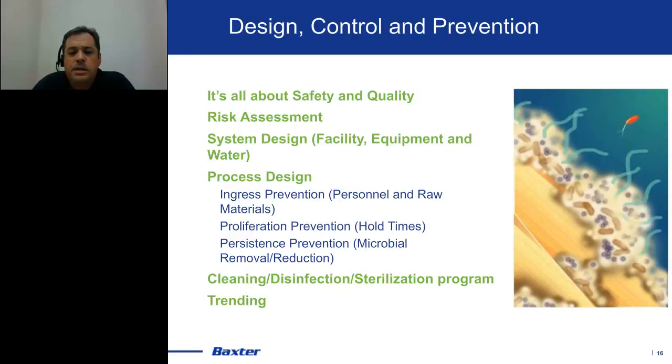And there is persistence and persistence prevention. What I mean by that is you can have microorganisms getting in, you can have them growing, but you can also have them surviving your treatment. So work on preventing any risks around those surviving that cleaning and sanitization. That can all be built into a cleaning, disinfection, and sterilization program, and then that should be trended. And we'll talk more about trending in a little bit.